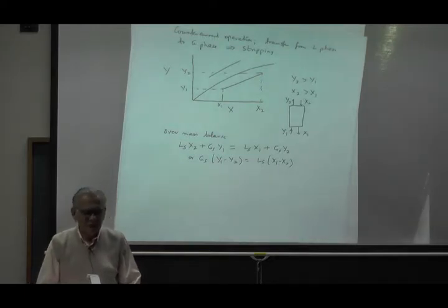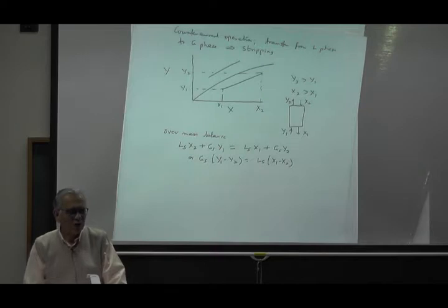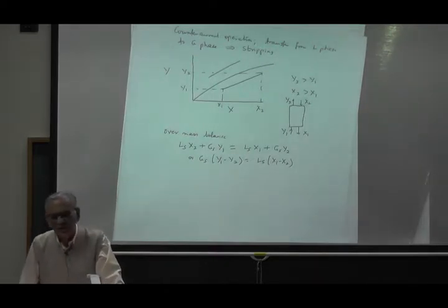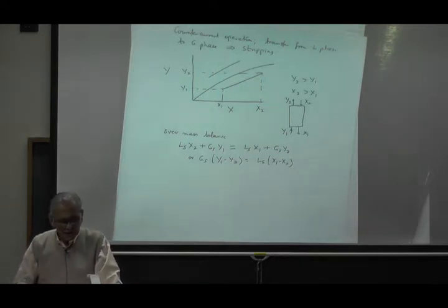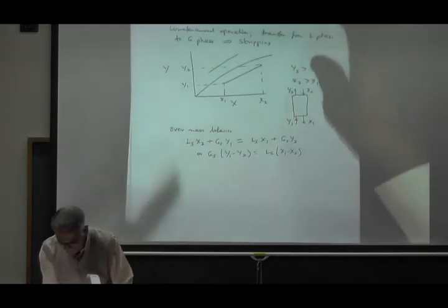If everything is mass, mass is also conserved. So you can work in terms of mass flow rates and mass ratios. But you can't have mass flow rates and molar ratios. So you have to be careful there, that if you are working in terms of mass flow rates, then there will be the mass ratios and mass fractions and so on. So you can work in either way.